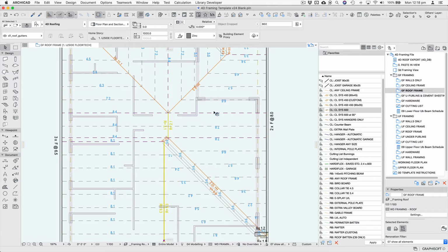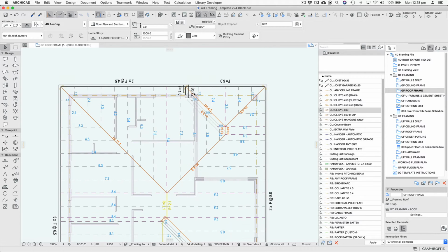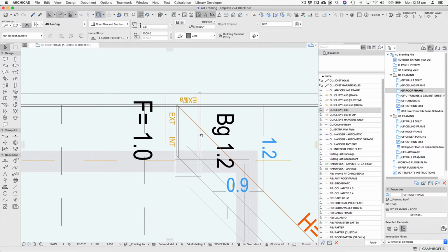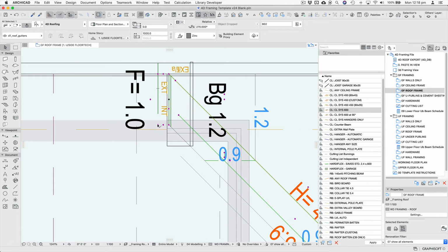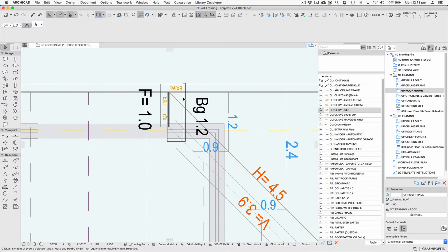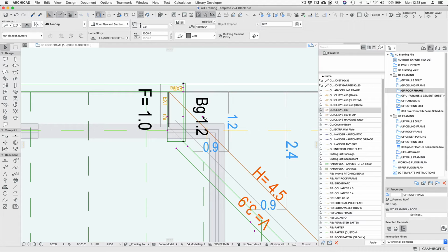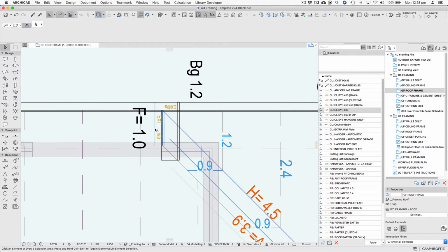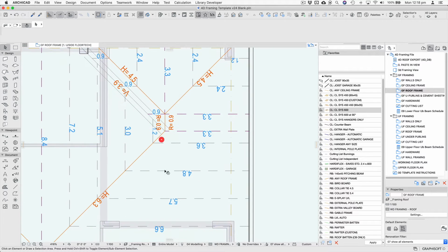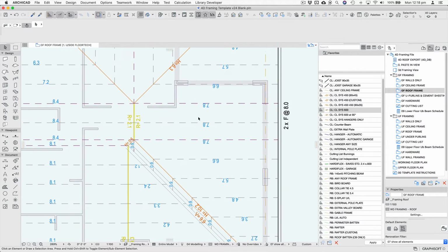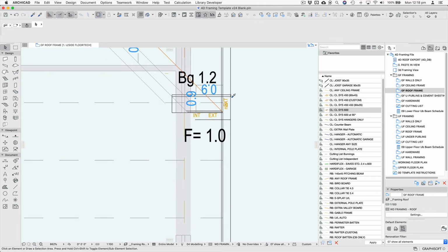Okay, next, wherever we've got some high sections of gutter, we need to just tell the fascia that that is not an internal edge. You can see that there. Here it's ordering a barge for this endpoint, which is fine. We can move the text around if we want, but I'm not going to do too much of that today because I'm trying to get this video done in as little time as possible.